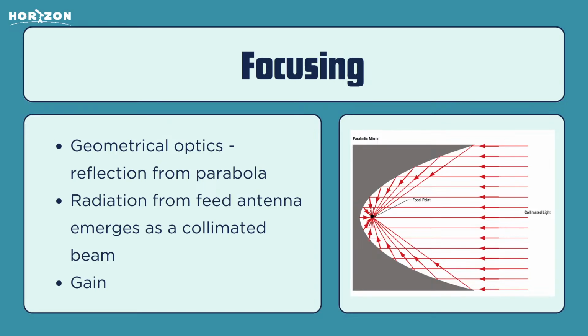The rays passing through the focus become parallel to the axis after undergoing reflection, so a collimated beam with a planar wavefront is produced. And for receiving signals, a plane wave traveling along the axis of the parabola converges at its focus, and this maximizes the signal received by the feed antenna.